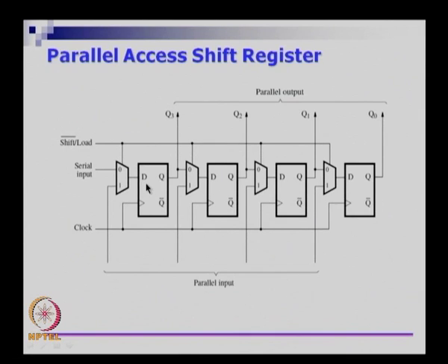So shift registers need more cycles for you to see what are the actual bits that are stored currently. And similarly, if you want to put a value into the register using only serial input, then it will need n cycles also. So loading the register serially takes n cycles, getting the values which the register has also takes n cycles. However, loading in parallel takes 1 cycle, reading in parallel takes 1 cycle.